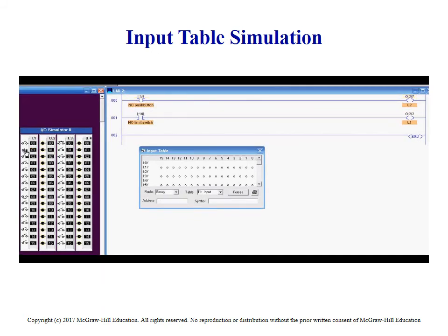But we'll be getting more and more into that in the future. So here we are looking at an illustration of data table and inputs versus outputs. As you can see here, when he makes this input, you'll see that switch from a 1 to a 0 here on the data table. This data table is being updated from this I/O card. So this information is being extracted from here and dumped to this location. It is our job as a programmer to know what location we're looking for, put that address here to extract the information from this location to here to turn on this output.